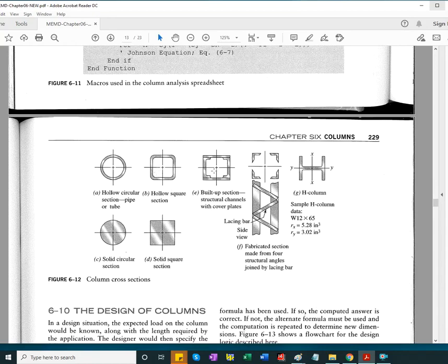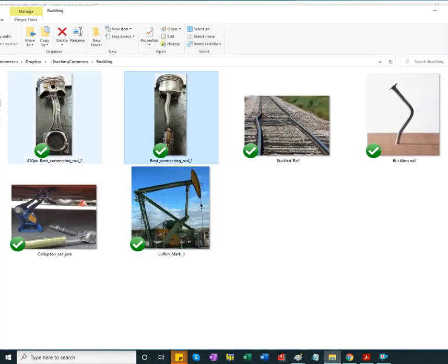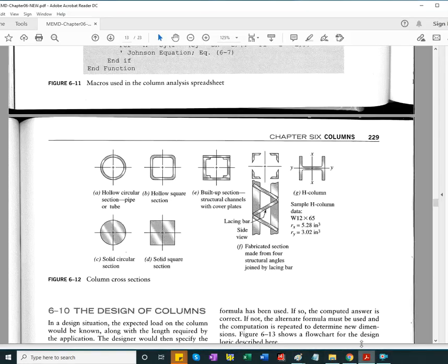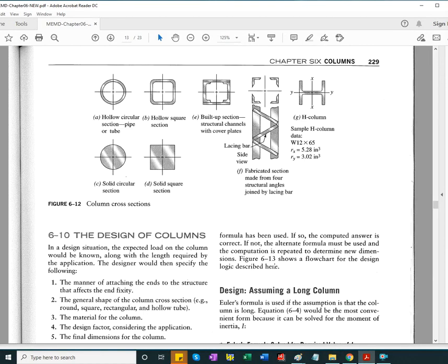Hollow square section, fabricated C channel with side plates, angle pieces, structural angles, braced I-beams. I-beams, that will be the case of, I'm going back to, yet again, these two images. So if you're to section somewhere here, you immediately recognize an I-beam as a section. I-beam being one of the good uses, providing good use of the material in terms of flexural stiffness. Okay.